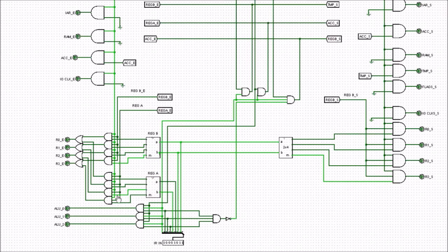So it's coming down here again into this AND gate, and it's trying to choose the value in register 2. But again, it won't choose it unless the clock enable goes high, which it is at the moment. But also, our register A will have to be chosen from this input line, and that gets chosen from some other part of the circuit. So some other part of the circuit will control and tell us whether you can actually get access to that register, but we'll see that just in a minute where that other part of the circuit is.